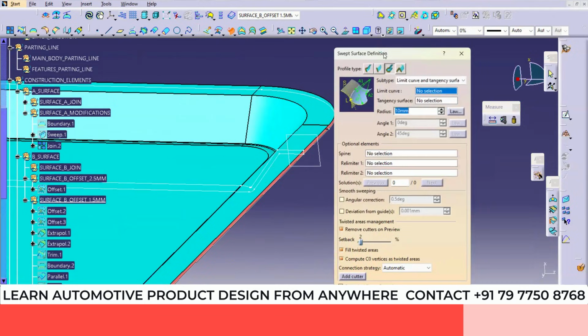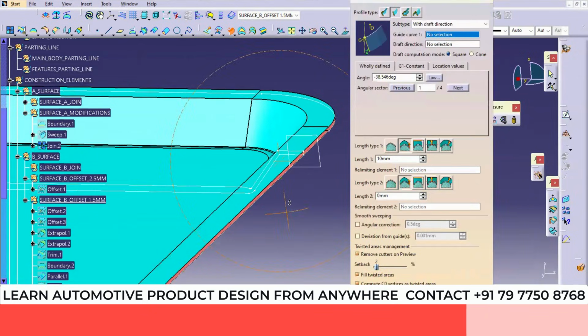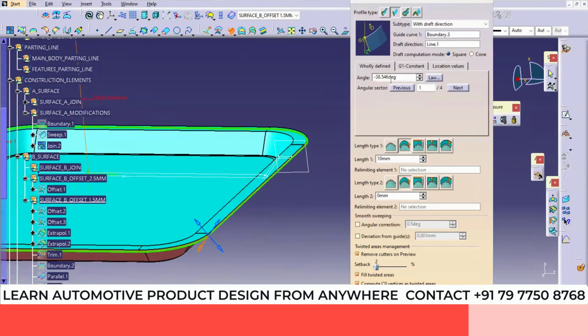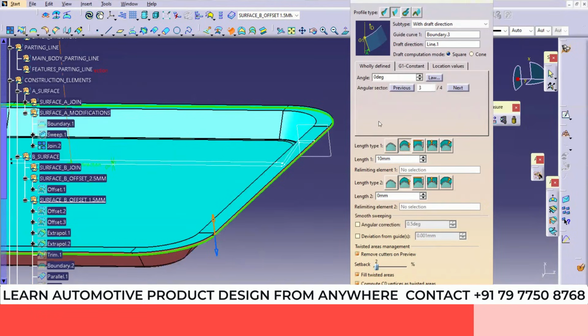Sweep command with draft direction or with reference surface, anything you can select. With draft direction, in this case guide curve is this, then draft direction is this, and then angle is 89, or 0 degree you can put. Draft is 1 degree, right, in this direction. 89 means 1 degree draft, right? 90 minus 1. So here you can put the 1 degree there.